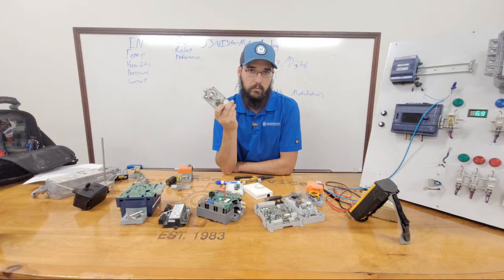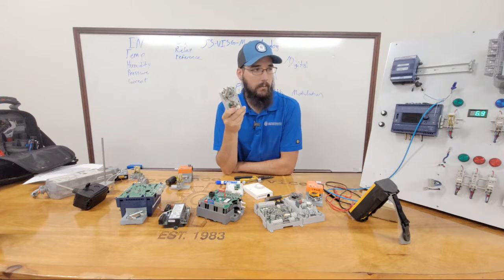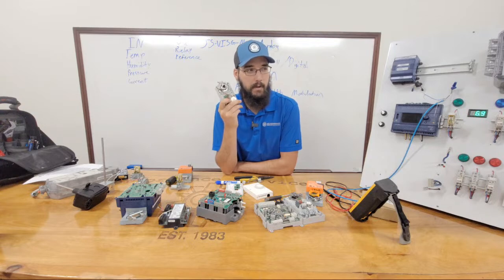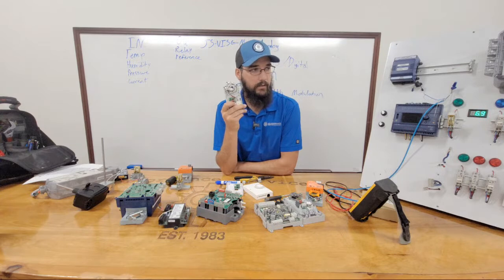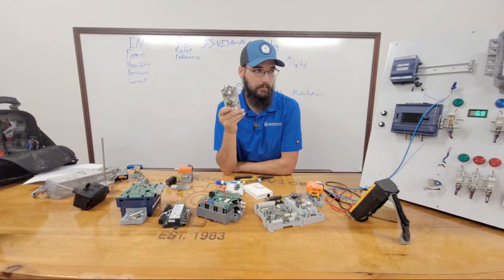So my rule of thumb, when I walk up and I've got floating points in the building, if I'm going to do a calibration manually through the automation, I will do the override, and then I will put a timer on my phone for at least 4 to 5 minutes. 4 to 5, not 45, 4 to 5 minutes.